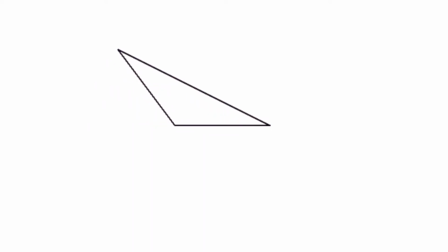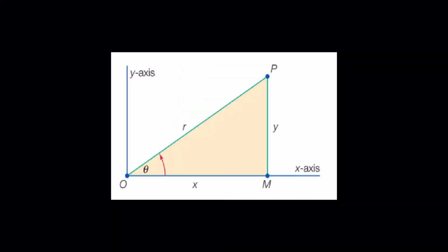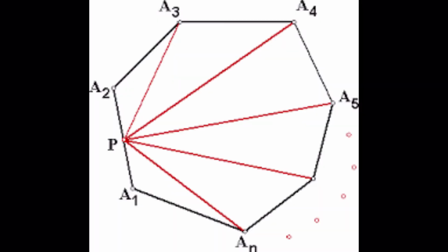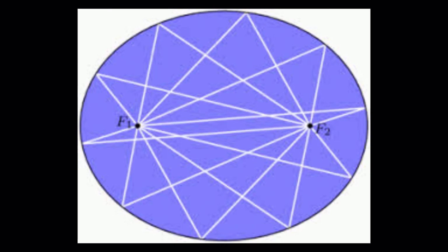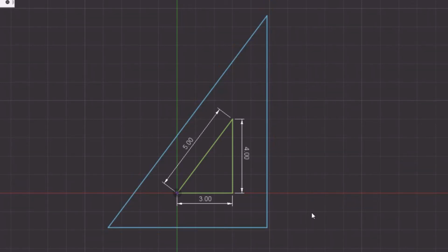So in this way, triangles provide us with valuable information that describes the spatial orientation of points. Any of their angles can be calculated when the length of the sides is known. This means that they can be used to record the size, shape, and angles of other, more complex shapes. This feature is especially useful when measurements are taken on a horizontal plane where plumb and level reference lines are not available, such as when measuring countertops. As if triangles weren't already useful enough, the 3-4-5 triangle provides a convenient way to lay out square corners.